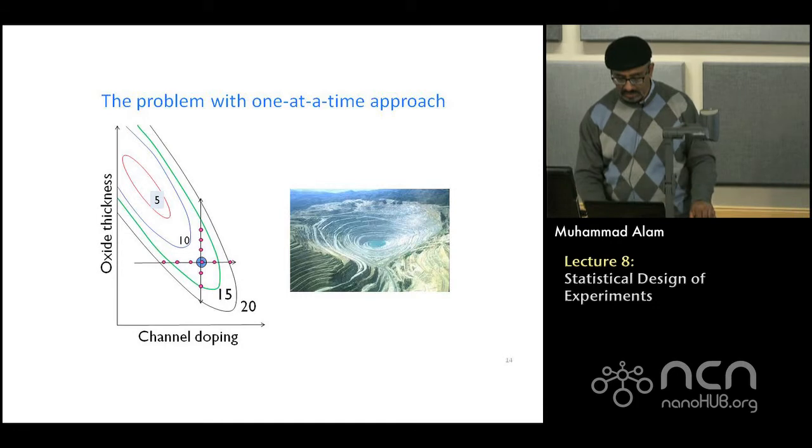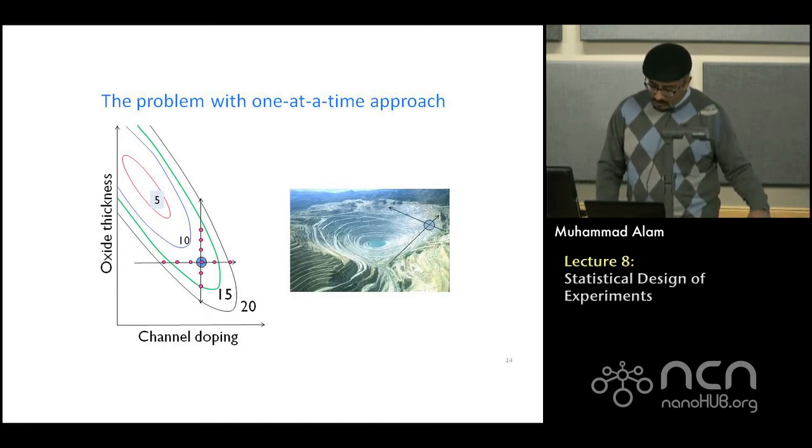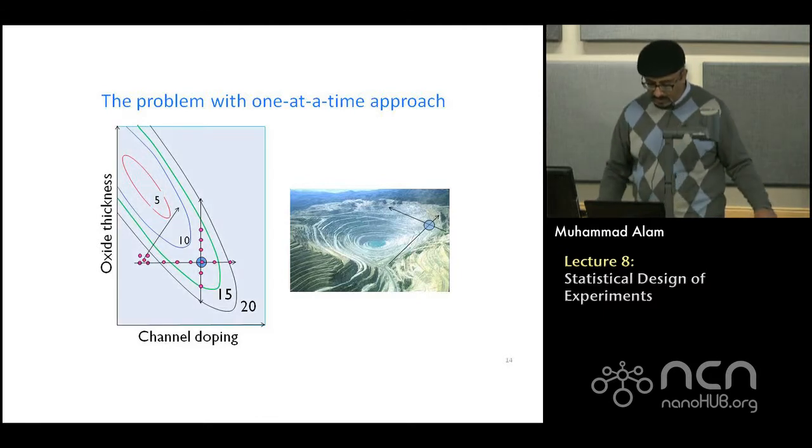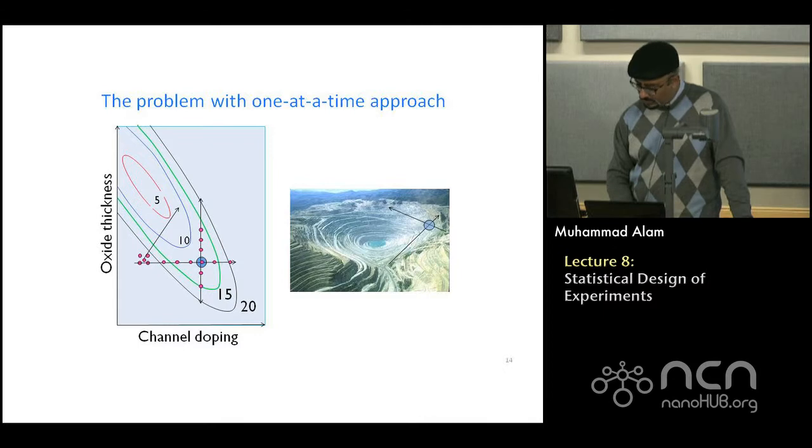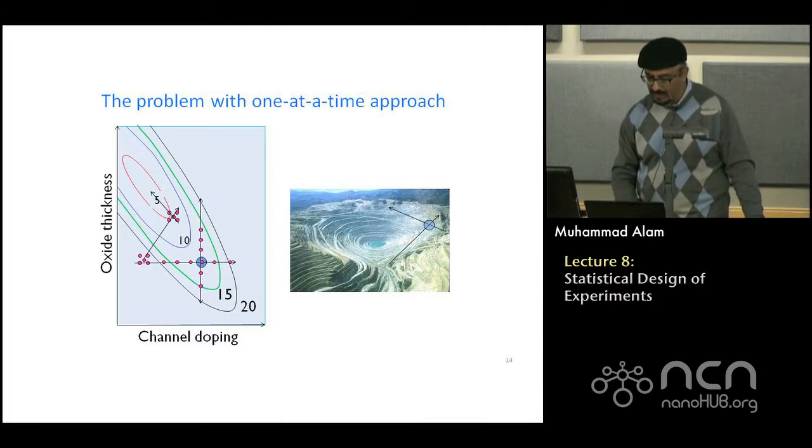That is the problem. So what do you have to do? There are many methods. One is called the response function method, and I am going to show Taguchi also a little later. What the response function method says is that you do 5 local experiments and look at the gradient. Instead of doing a lot of experiments like this, just locally probe which direction the water wants to roll. And you do that experiment, and then here you do 5 more, and 5 more here maybe.